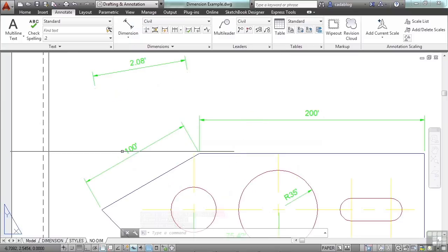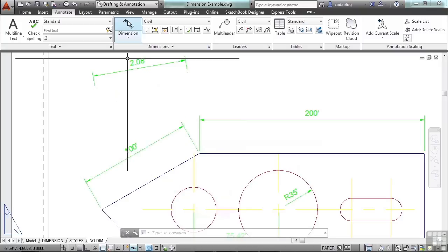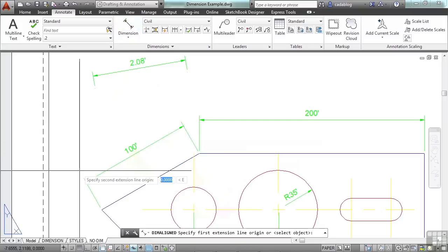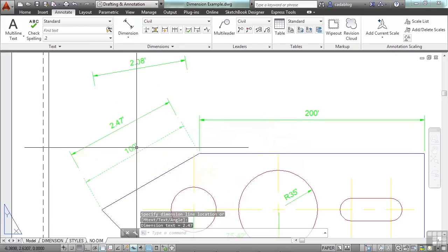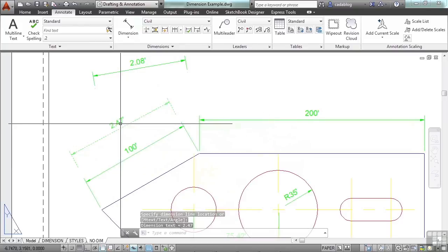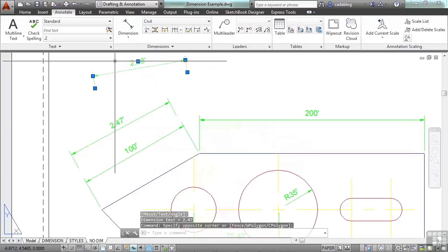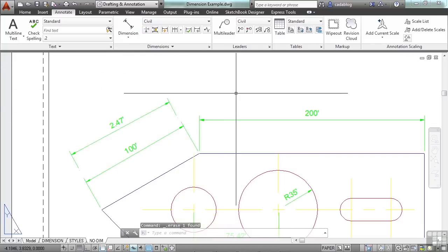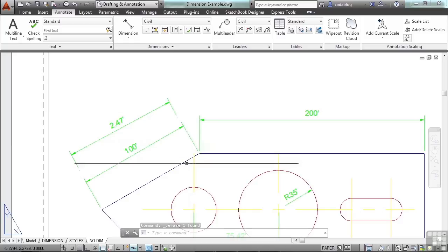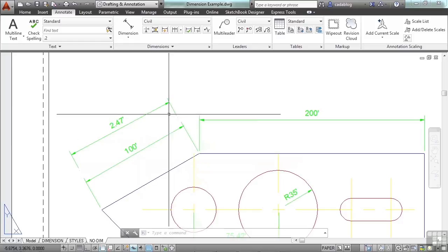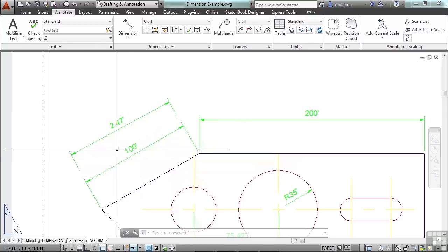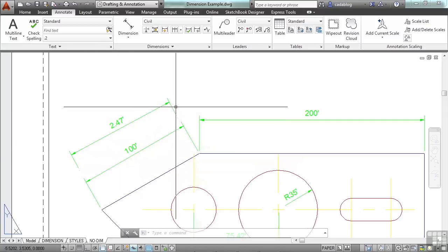Now you notice that this says 100 feet. Now if I were to click up here, in approximately the same distance, see, well, why is this 100 feet and this is 2.47 feet? Let's erase that to get it out of the way. Well, that's because when I used my O-snaps, it snapped to the line work that's in my model. Here, I'm snapping to nothing, so it's picking the paper size length. So when we print this out, this line is going to be about 2.5 inches long.